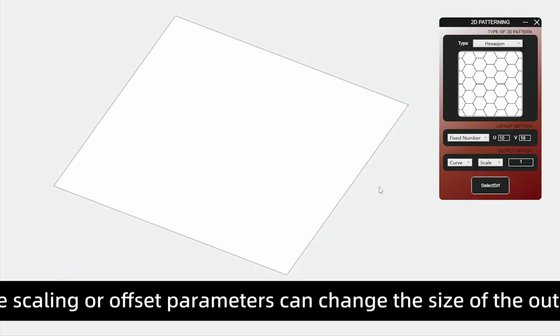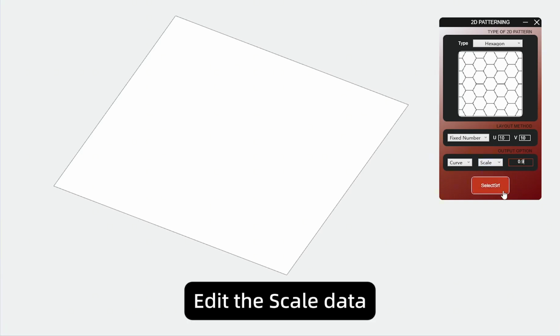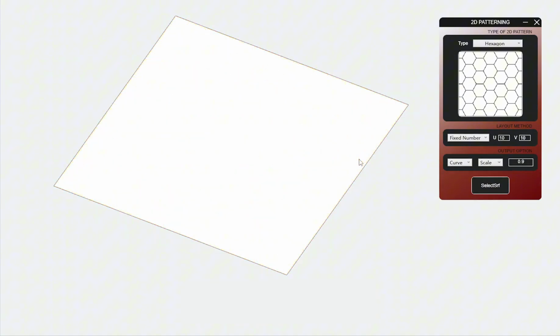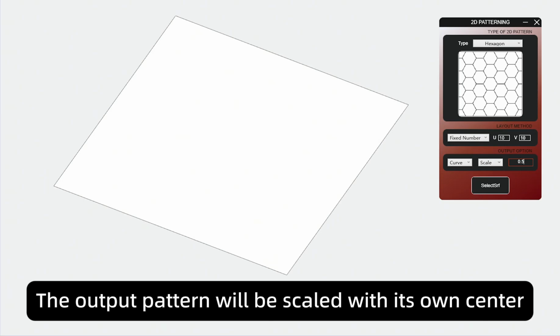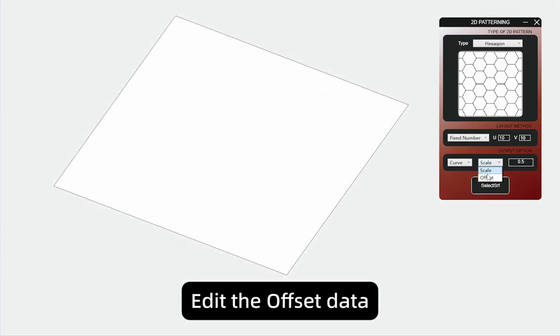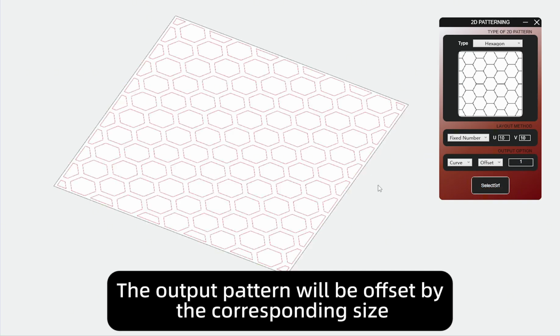Editing the scaling or offset parameters can change the size of the output object. Edit the scale data. The output pattern will be scaled with its own center. Edit the offset data. The output pattern will be offset by the corresponding size.